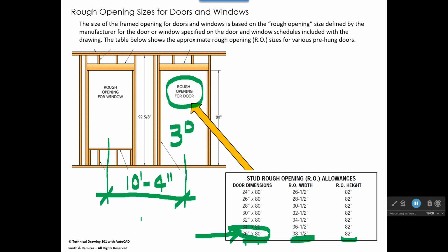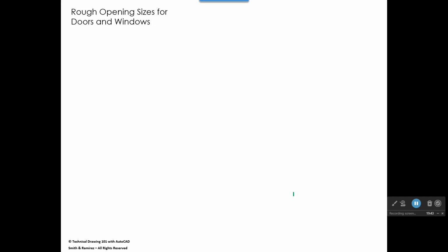Now, like I said, with the National CAD Standard, the National CAD Standard is starting to put arrowheads in, and so you might go to work for somebody and that's what they're using. But we're going to show you the traditional way to draw these today. And then later on, when you take the commercial class in our department, or you take one of the residential classes, they may use a different dimension setting style. And so all of this stuff that we're doing right here, the way we're setting it up, this is going to be in your dimension style, just like it was in the ASME drawings.